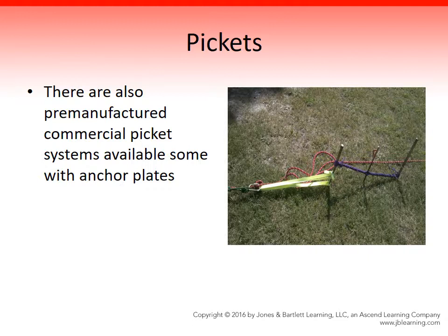When driving the pickets into the ground, drive the pickets at a 15-degree angle. Connect the pickets in each row by lashing from the top of the first picket to the bottom of the next picket close to the ground.